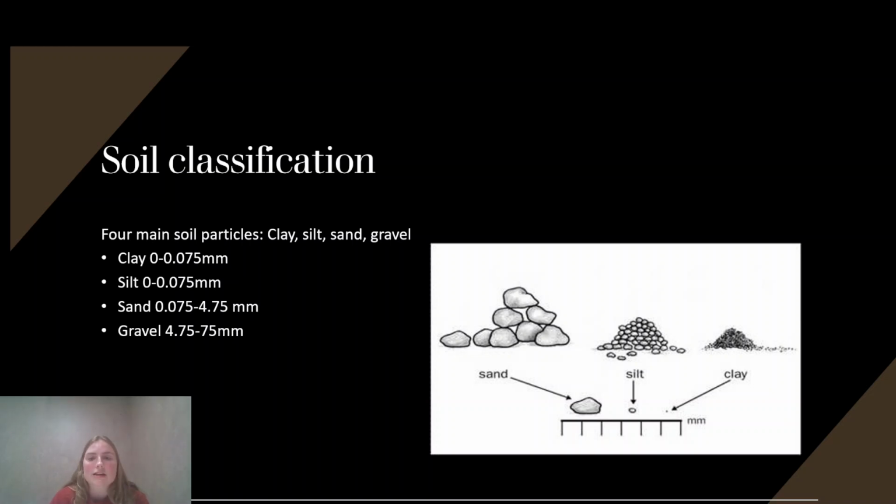So pretty much they act differently when water is added into the soil, and that means all their engineering properties and the way they behave when load is applied on top is different. Clay tends to slip, whereas silt has a little more friction between soil particles, so they have more resistance to load than clay does.